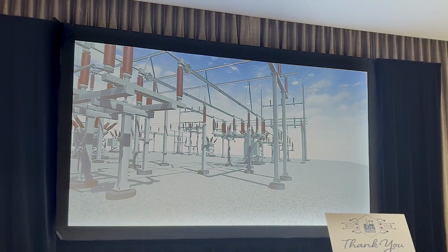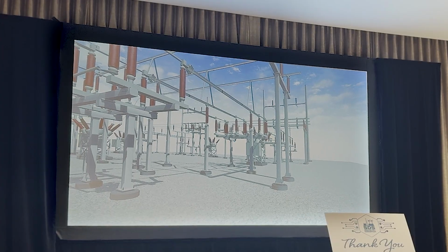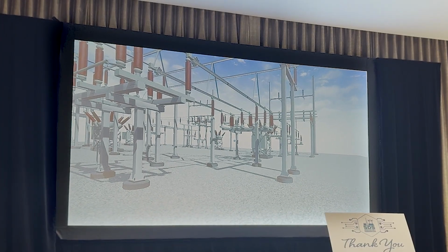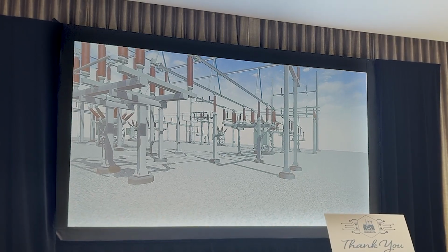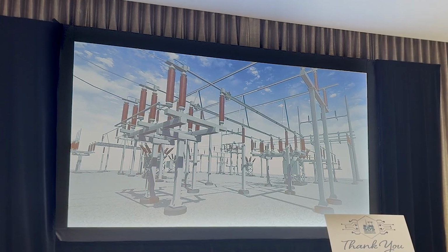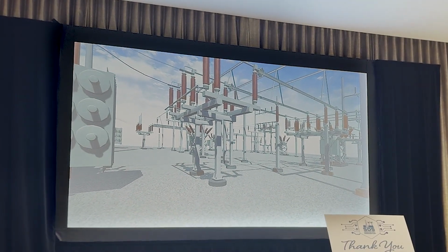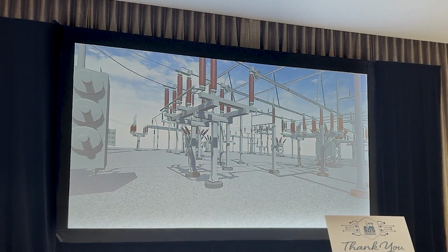So you can see areas where the bus hanging low actually causes a hazard, because the envelope of protection with that phase to ground clearance gets low to the ground. You can tell areas where you might not want to put a vehicle too close, or might not want to walk. That's some enhanced functionality. You can also tie all kinds of metadata to this model, like photos and asset data and all that kind of stuff.